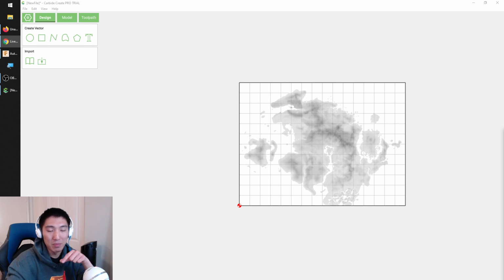I would say try and minimize your retract height above the stock. The default is like 0.1 inches or something, and if you retract that far and have to plunge at like 2 inches per minute going back down, it'll take a while. So just minimize that height if you can.